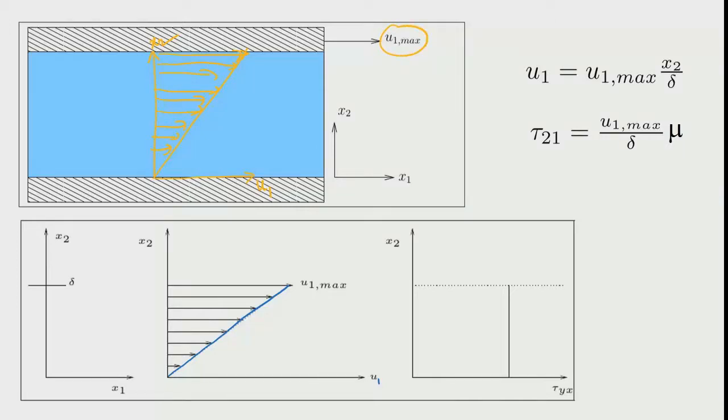And we can also see that the Newton's law we have retrieved, because when we now see that the shear stress is calculated as per the same formula, then it comes out to be a constant, and we can see that here it comes as a constant because u1 is constant and delta is in the denominator, and u1 is positive because it is along the direction of x1. So, which means that tau 21 is positive and it is constant. So, that is why the plot of tau with respect to x2 is just a constant vertical line, that is going like this.